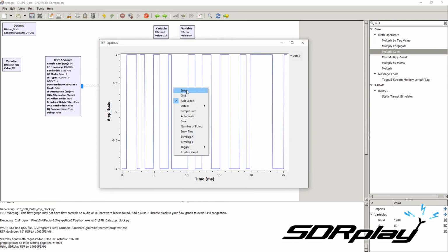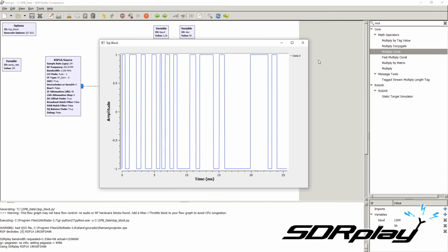Now the only thing that's left to do is to turn this into a bit stream. So we know, for example, let's say that this one is a 1 bit and this one will likely be a 1, then the next bits will be probably 2 zeros, because you see the length of the signal is double the length of this one. So we'll need some way to transform this data to 1, 0, 0, 1, 1, 1, 0, 0, 0, 1, 1, 1, etc. To do this, we'll need to use some synchronization method that we will see in the next lecture. So that's all for lecture 7.